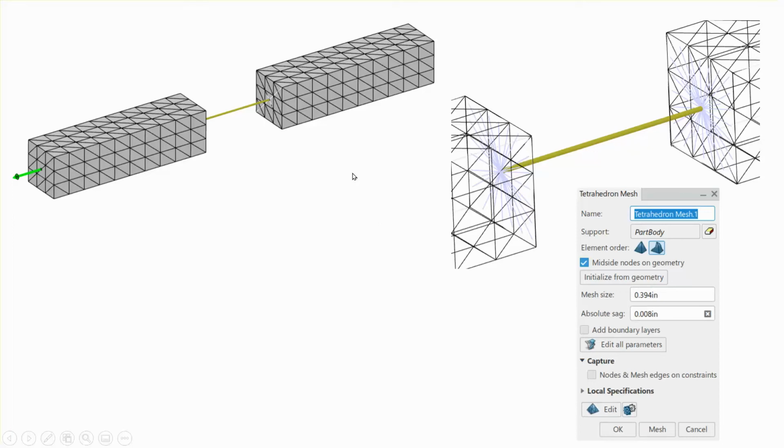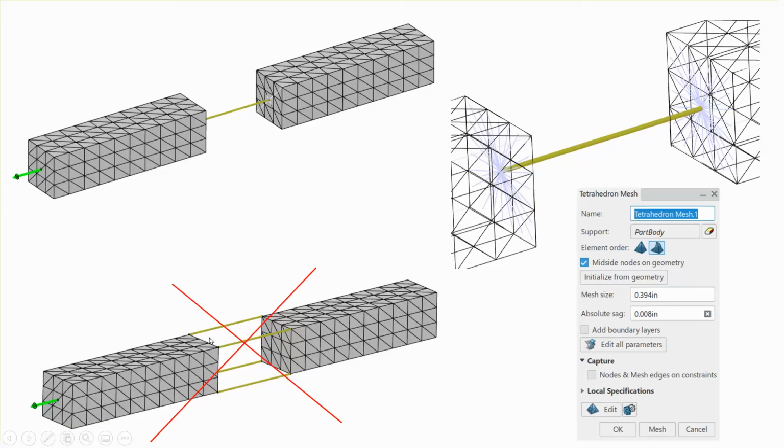Now, I'm going to do this the way it's described here, creating a rigid connection between the two end faces. It is done with the spider element that you can see here. I'm going to do it like this. It can also be done as four rigid connections, think about a rigid beam, at the corners.